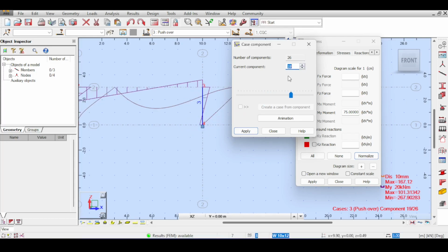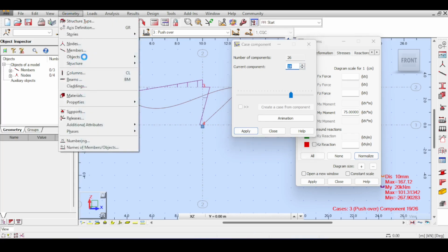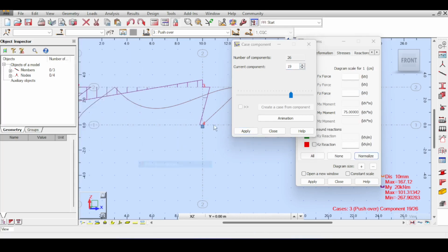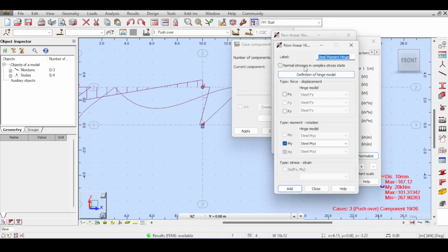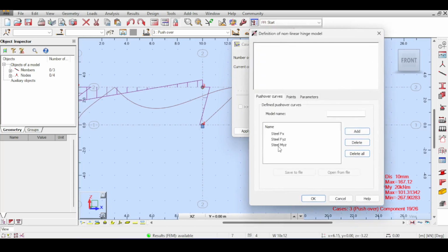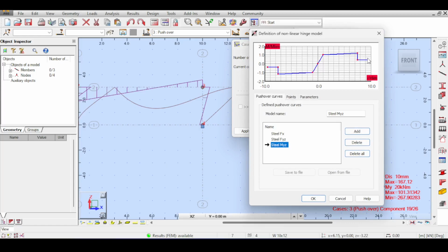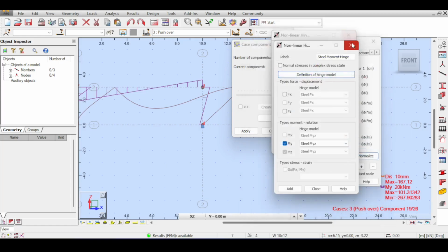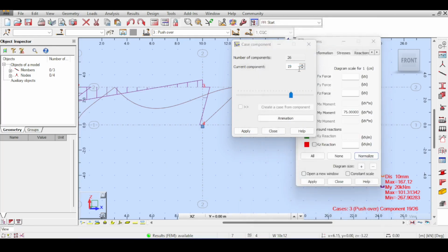The hinge at 4 snapped, because in our definition for those nonlinear hinges, to show you very quickly, in the definition, you see that it snaps. You can see that after a certain position it snaps and then it goes to 0 again. So what I'm expecting is, I mean, this is beautiful. Oh, look at this. You see it totally snapped to 0. This is exactly what I want to see. This is gold, to be honest. You can even see that this one plasticized, it's not snapping yet, but it doesn't increase in moment. And you can see that it didn't snap.